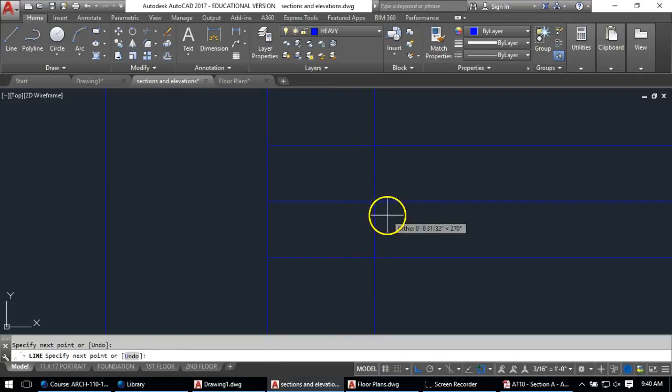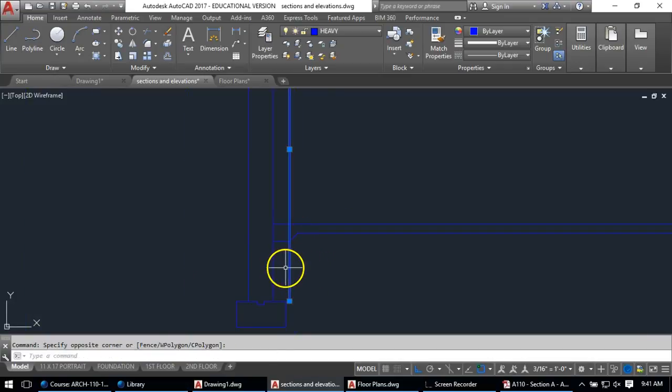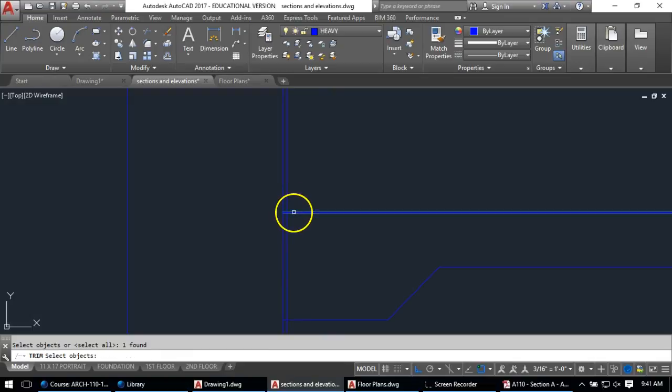What I'm going to do is draw a line up and rotate this little line I just drew 45 degrees. I actually did negative 45 degrees to make it go in that direction. And now I can fillet that to that, and this to that over there, and I can remove this guideline. And we have this little sort of expansion joint in there, so I'm just going to offset that like 1/4 inch. Could have done maybe 1/2 inch or something, but I'll go with 1/4 inch. Put that little line in there, put that little line in there.